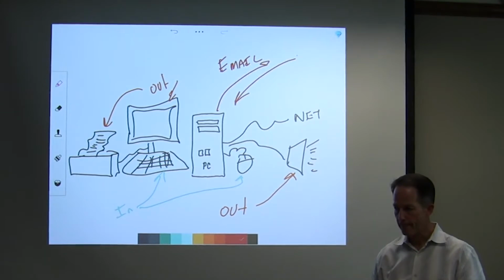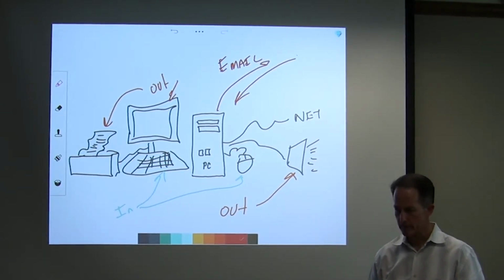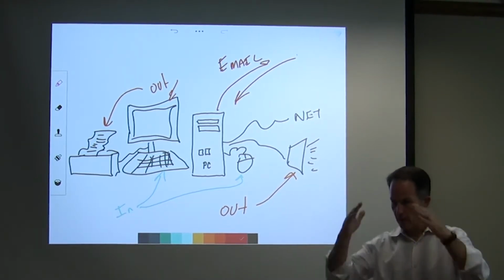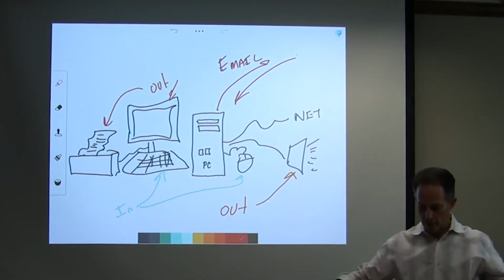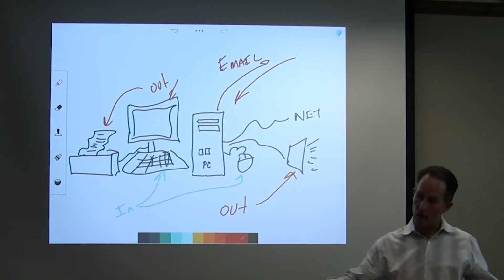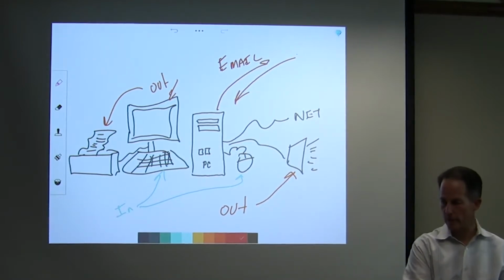So that's the change that we made when we used to have to log in to see things. Now there's just one login because it's on the supervisor. Right. So the idea is that it's kind of like a pyramid thing, right? The very top, the supervisor has access and supervisory control over all of the Jaces. They then have control over all of their devices underneath them.